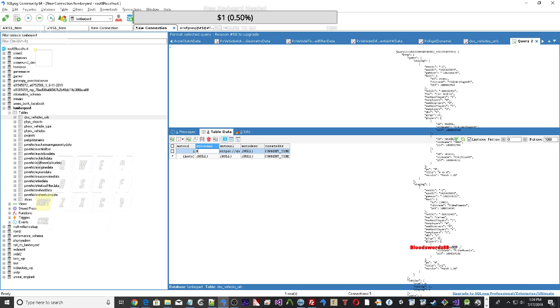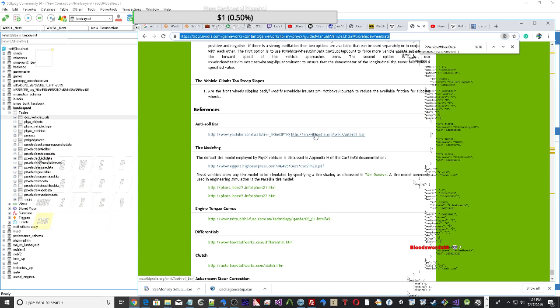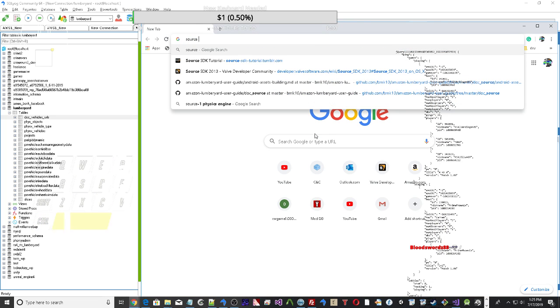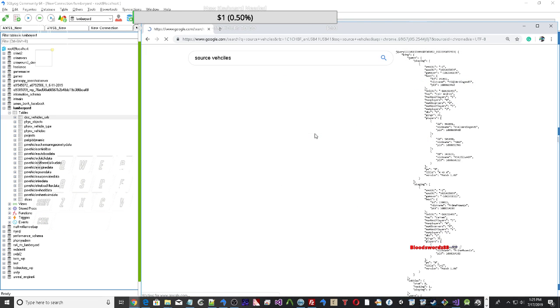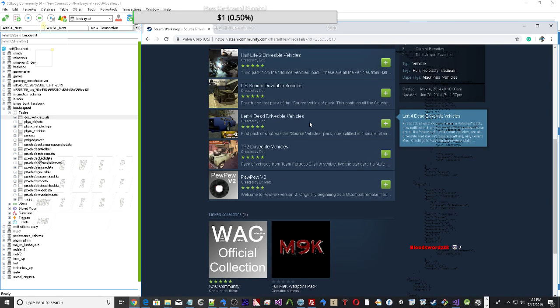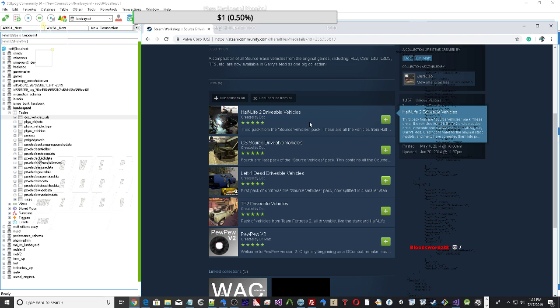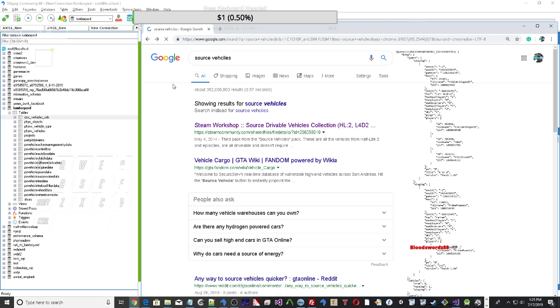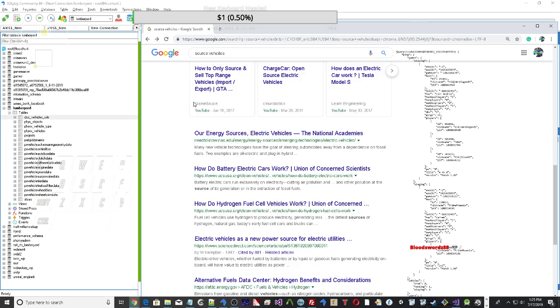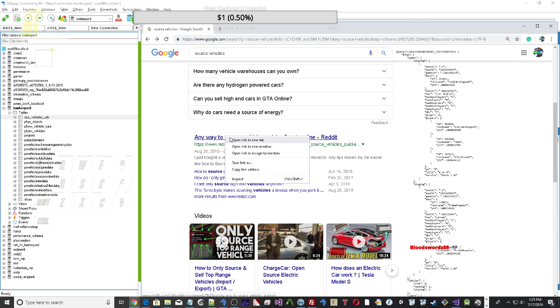The PxBatchQuery instance is typically instantiated as part of the initialization phase and then reused each frame. It is possible to instantiate a PxBatchQuery instance for each vehicle, or to instantiate a single PxBatchQuery instance with buffers large enough for all wheels of a batched array of vehicles. The only restriction is that all batched vehicle arrays and associated buffers configured at the start of a vehicle simulation frame must persist until the end of the vehicle simulation frame.